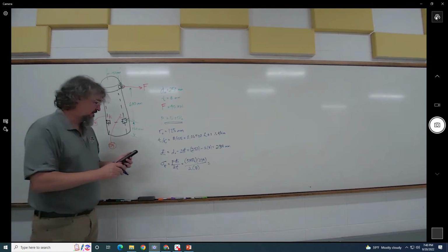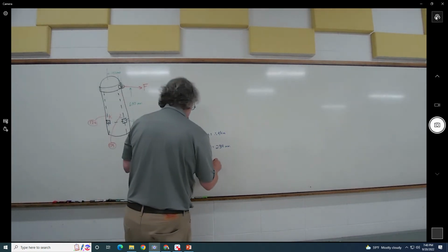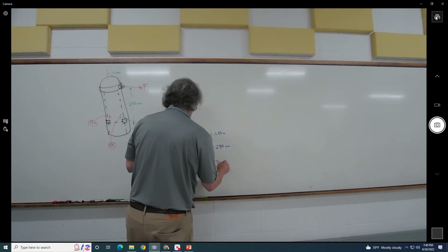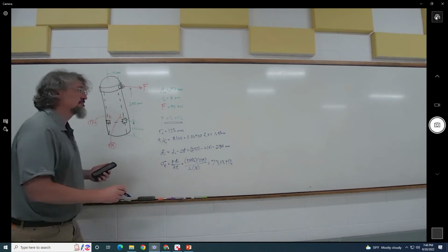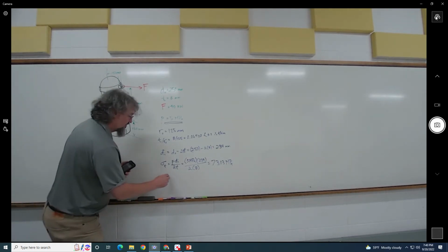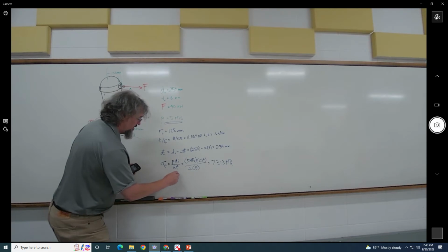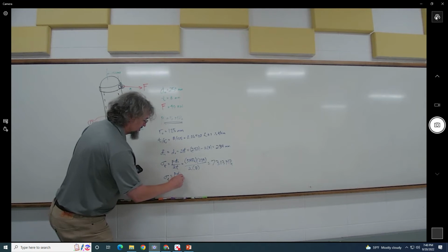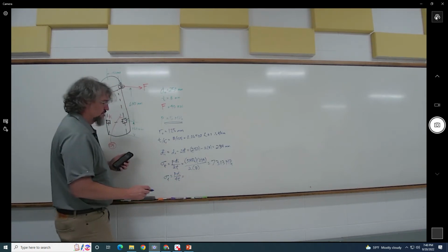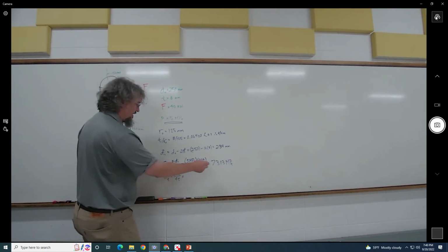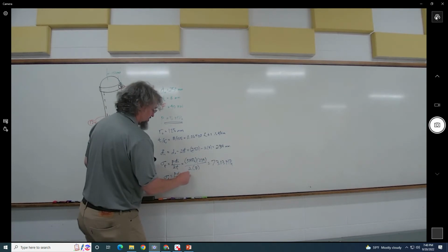So we have a substantial 73.13 megapascals. It's nothing to sneeze at. The longitudinal stress is just P di divided by 4t. So you really could just divide this one by 2, right?